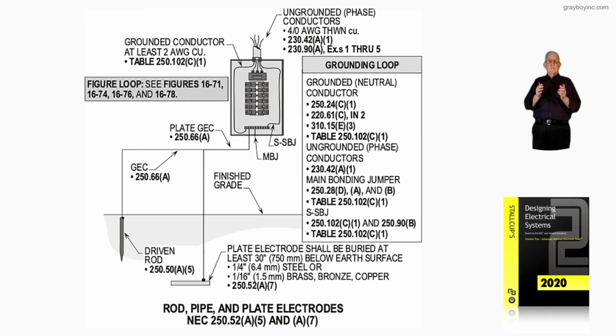And then notice 310.15(E)(3), we use (E)(3) to determine if the neutral in the system under certain conditions is current carrying. Basically, if a major portion of the load on the neutral is harmonically or non-linear loaded, as we previously stated through this presentation, the neutral's current carrying.